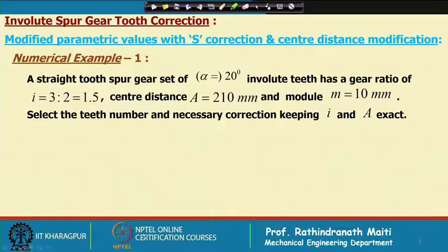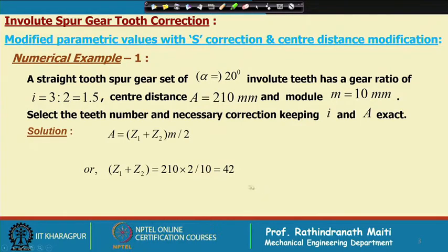The answer is that this is a specific purpose gear, and in such a case we have to make it the exact ratio, and it should usually be precision gears. We cannot take rough cut gears, we should make the gear set as precise as possible. Okay. Now, let us see what we can do.